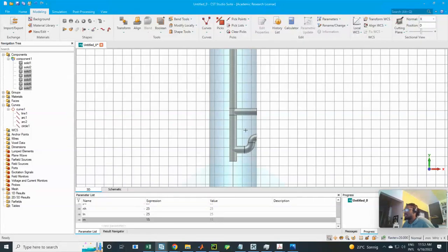Now, the goal of this is to define your geometry with as few dimensions as possible, because then when we want to tune this we have fewer parameters to work with. So it's defining it completely but using the minimum amount of dimensions. I could just create another offset and then we have that, but I'm trying to drive it with some other dimension. So we could just define this length from this point and then it automatically shifts it. So I'll be right back.